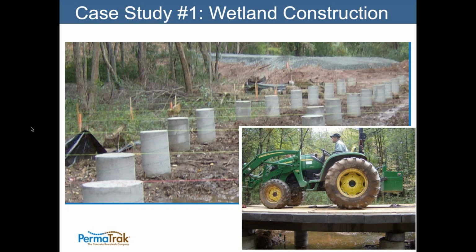So imagine construction equipment operating between the piers. The piers were spaced far enough apart that the drill rig could operate between them. Once the piers were built, the regulators did not require the installer to be traveling up and down and continuing to damage the wetlands. And they did that by top-down construction. You can see from the picture, this particular installer chose to use a mini tractor. Product was delivered by the tractor, and then an excavator reached out and set the product in front of them as they went.